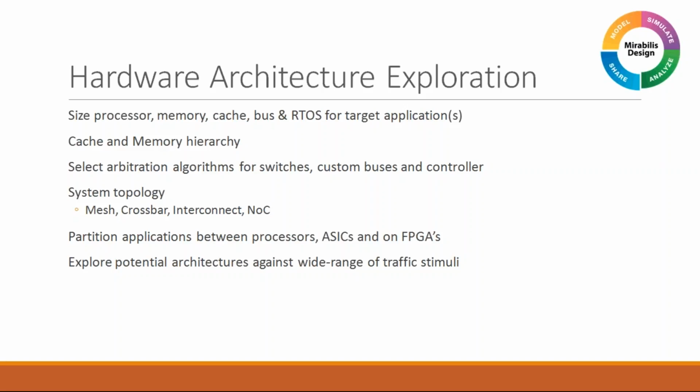how many levels of cache or memories that he has to use there. And also, in addition to that, the distribution of tasks between multiple cores of a particular processor as well. And with regards to memory hierarchy and cache memories itself, the libraries are extremely detailed and very accurate library blocks. And these actually enable you to read and write the data to a particular memory location, and try to understand what is the performance that you're getting if you're using a particular memory technology from Micron or Samsung or things like that, along with your processor subsystem as well.